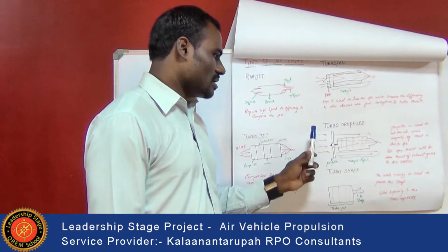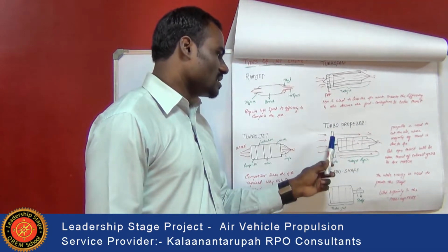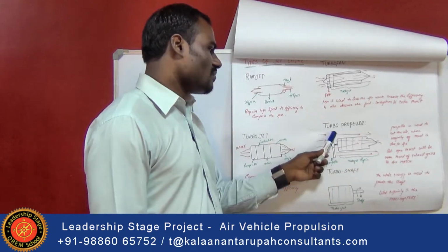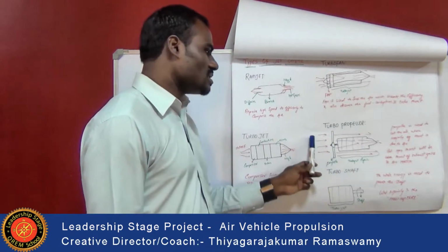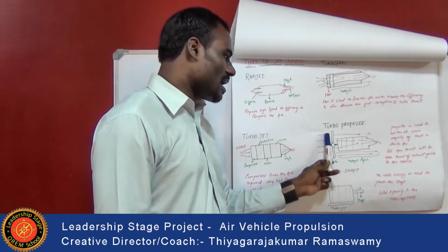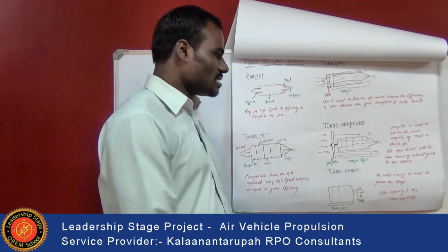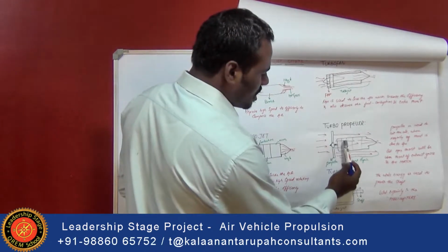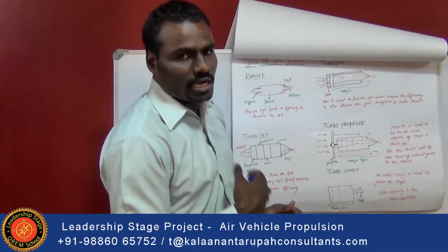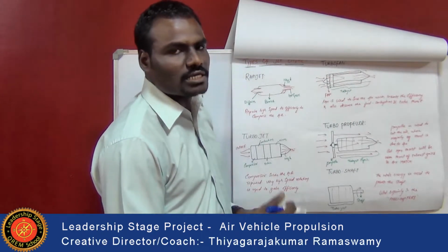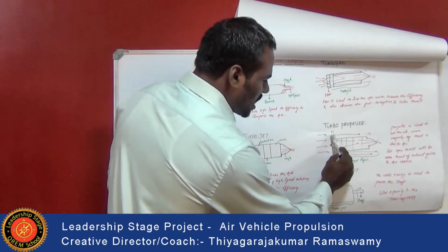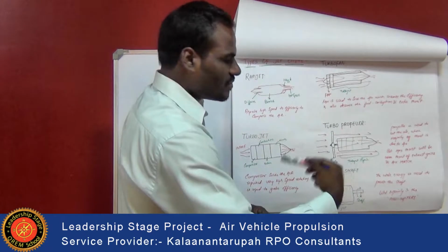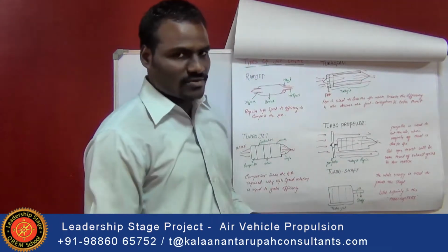The turbofan consists of a fan with a maximum diameter with respect to the nacelle structure. Here the fan is situated outside the nacelle structure, which sucks air inside the nacelle structure, so that only a smaller quantity of air is subjected to the combustion chamber and used for the combustion process, and then subjected to the turbine. The rest of the air, which is flowing over the surfaces of the nacelle structure, is used for thrust reversal processes.